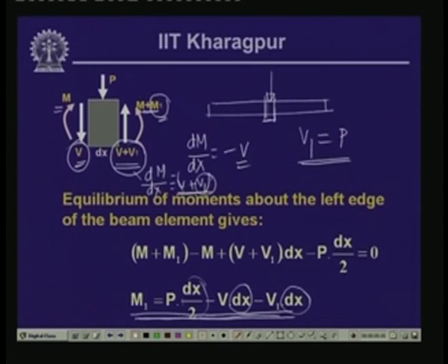So, though there is no change, or an insignificant change, in the moment value from the left hand side of the concentrated load point to the right hand side, there is a significant change in the rate of change of the moment. So, dM dx will undergo change when you have a concentrated load, and again we will be looking into that through the examples.